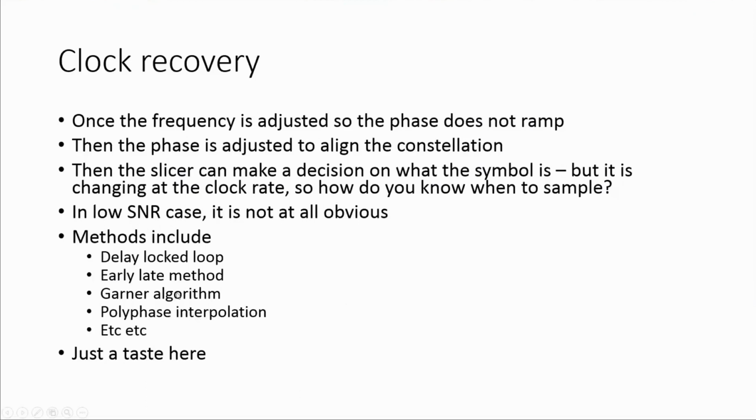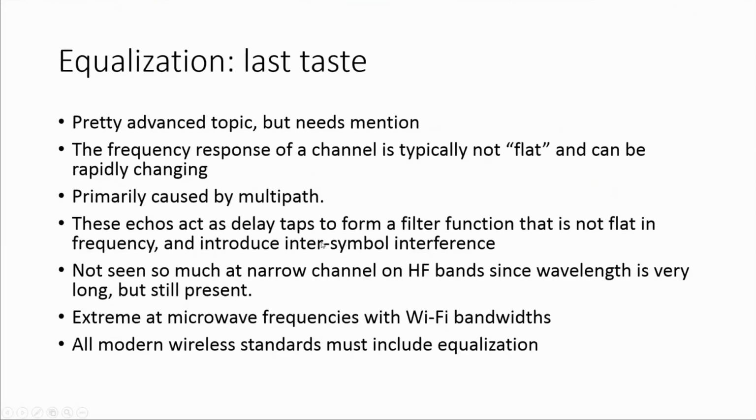So these algorithms have limited ability to recover clock that's very far off, more than say 1% is very far off. And especially if the rate is changing, they can often fail, but polyphase is better for it. So here's just a very, very brief taste of clock recovery.